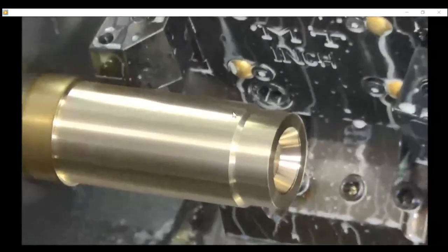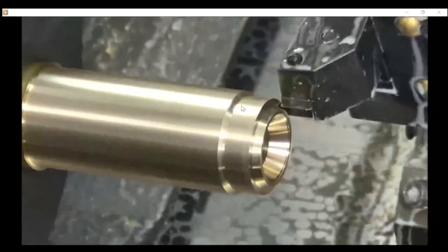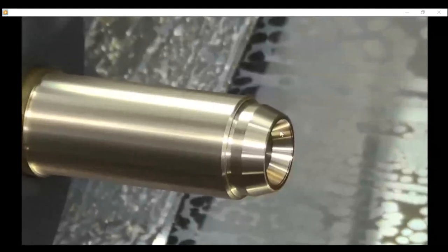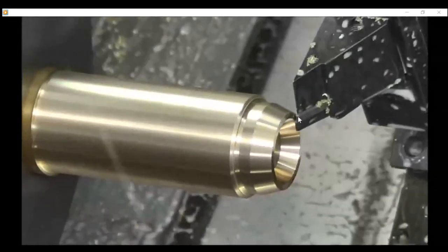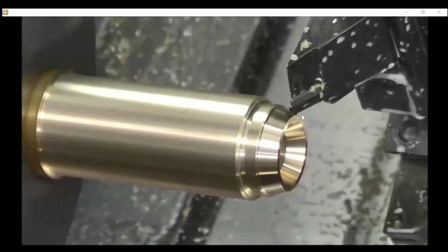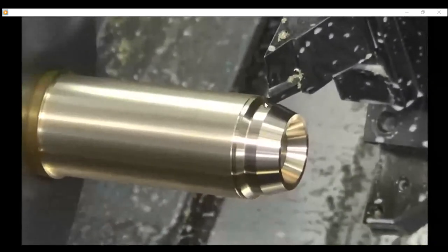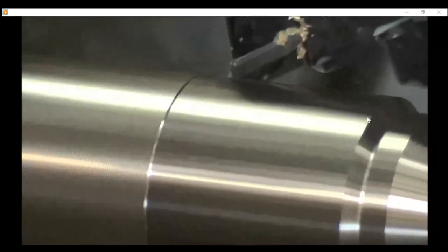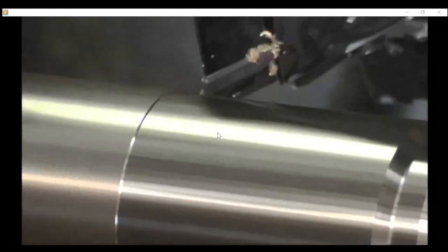This is rough cutting. We're removing a big amount of material. So cylindrical shape. Can you see that? This is the taper cut. This is the facing taper cut. This is facing, right? This is the finishing now. This is a taper, this is a straight, this is a taper, this is a straight with a small depth of cut, small feed rate, and higher cutting speed, then you can do the finishing cut.